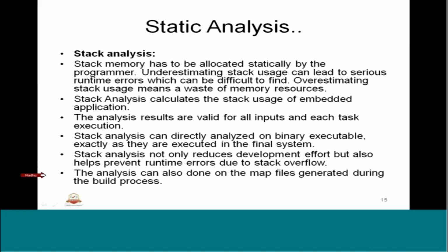The analysis can also be done on the map files generated during the build process. So we know that the program will be compiled, linked, and as a result we have an executable with a map file. Basically, the map file will have the complete picture of the program which is going to be executed on the processor.